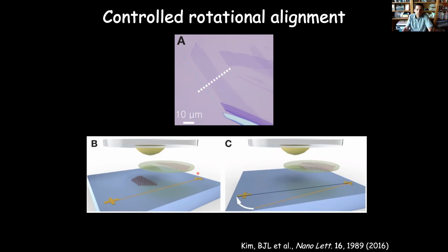Schematically, we take a relatively large piece of graphene, and we bring our PDMS/PC stamp down and contact just half of it. We make sure that we only touch down on half of it, and then we tear that part off. We tear along this white line, and we pick up only the top half of the graphene. Then we have this graphene on our stamp.